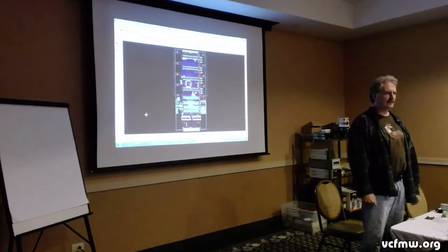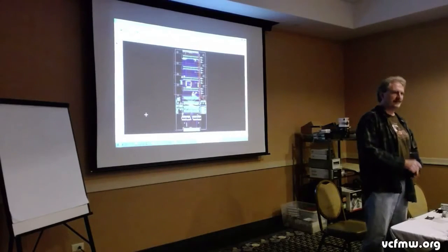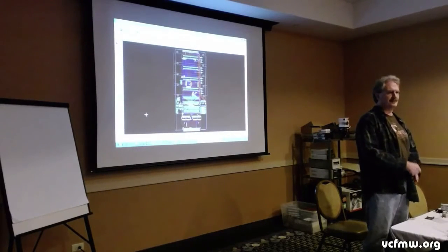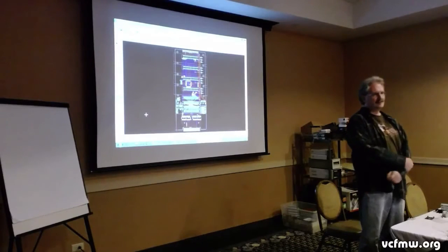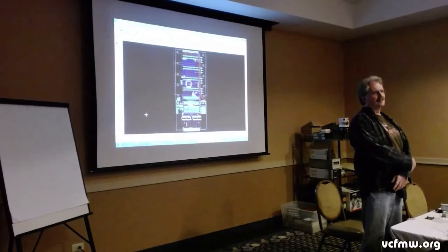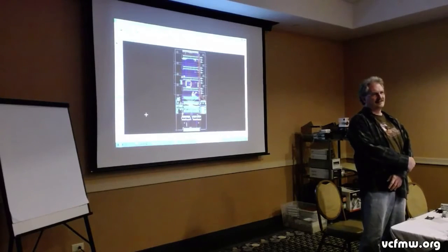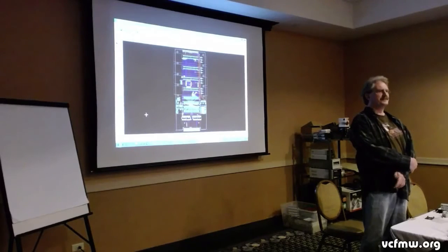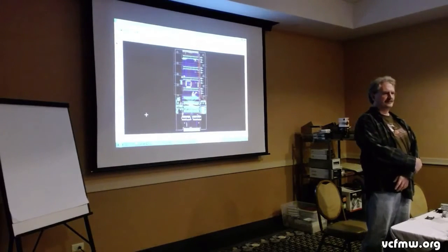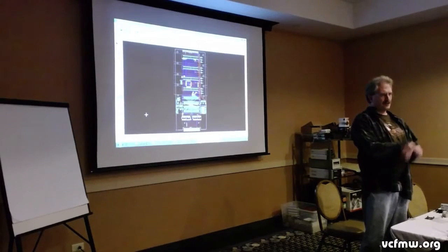There's two types. There's dual VCC buffers, which have an A side, B side, and run on the rails. And then there's also what's called a quick switch, which is simply just to accommodate that, where both sides are normally high until one side pulls it down, and it goes down the other. The downside of quick switches is you can't sink large amounts of current because the current is still sunk through your FPGA I/O. So for an bus interface or something that has like a 20 to 40 milliamp drive, that's where you use dual rail.